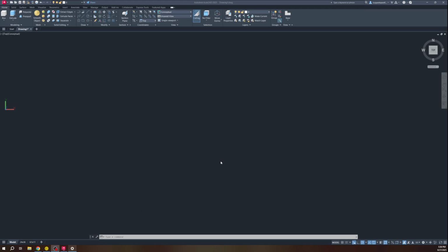There are two ways to create three-dimensional shapes in AutoCAD. You can either do that using the three-dimensional primitives, directly creating those three-dimensional shapes with your command, or you can extrude a two-dimensional line, a closed two-dimensional polyline, into the third dimension to give it shape. We're going to go over both of those methods in this video.